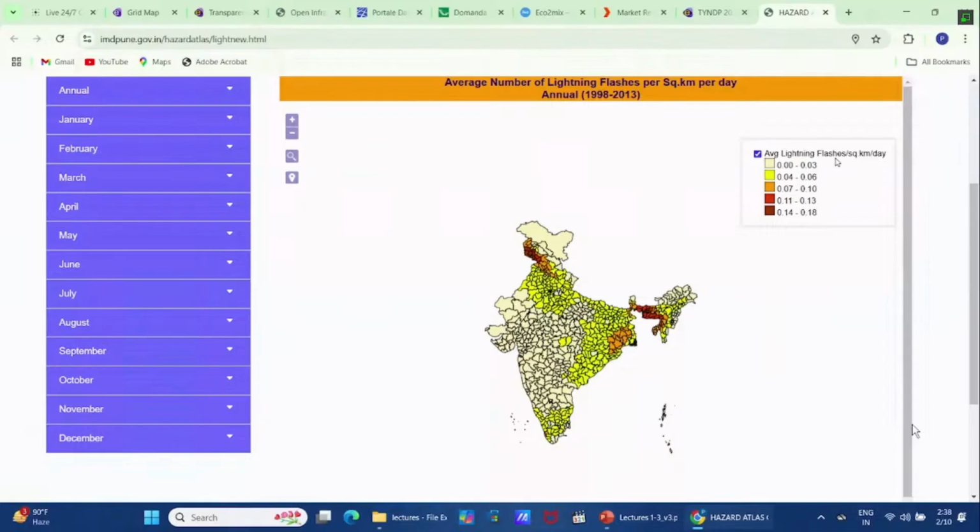Until now there is just the charge, but now there is the current, a current wave shape that propagates from the structure, from the ground, to the top at a speed that is a fraction of the speed of light, typically one third of the speed of light, no? Okay. This is called a stroke.